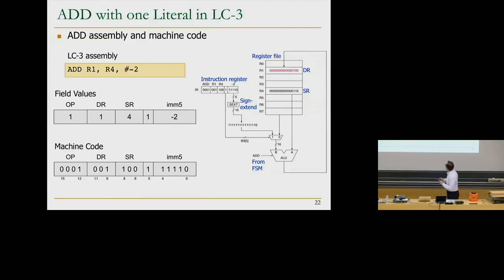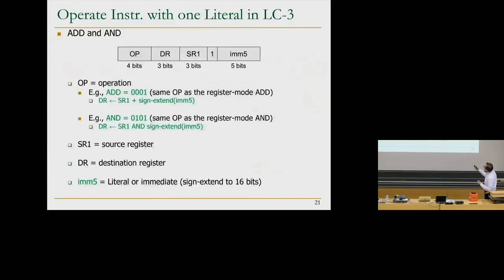Okay? So basically it's very simple. I've given you a little bit more complicated thing over here, which is this one. This one is cute, and you will figure that out when you read the book. Basically, bit 5 in the instruction decides whether you should take the immediate value as a second operand of the add operation, or whether you should take the value from a register. So if you go back to this slide, this 1 bit actually is important.